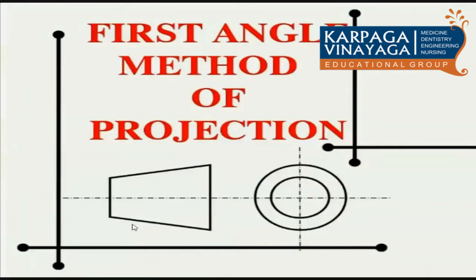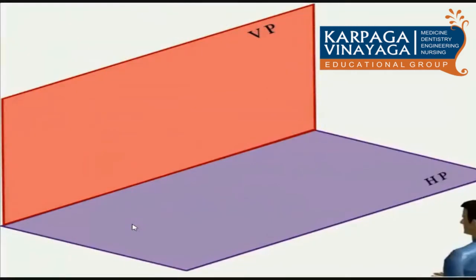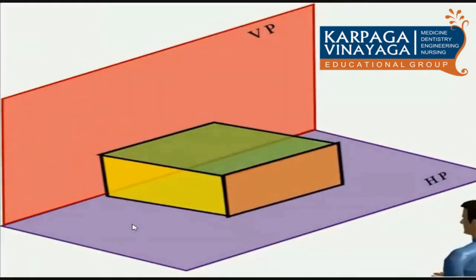Let's see the first angle method of projection. This is the front view. This is the first quadrant. The object is kept in the first quadrant. The front view is projected on VP, and the top view is projected on HP. When viewing from the front, only the front view is visible in VP. HP is not visible because it is the top view, so HP is the invisible plane.